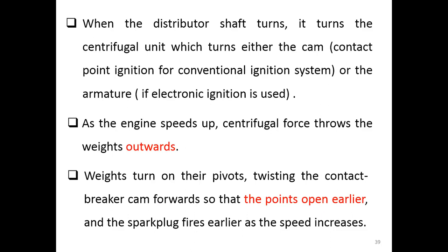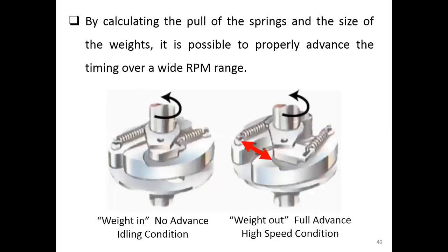So the contact point opens much earlier. So the spark plug will fire earlier. It works together like this.